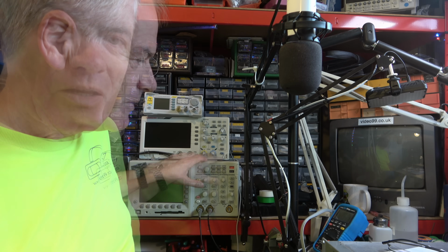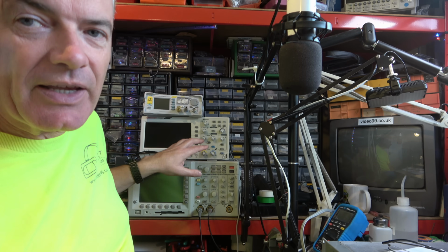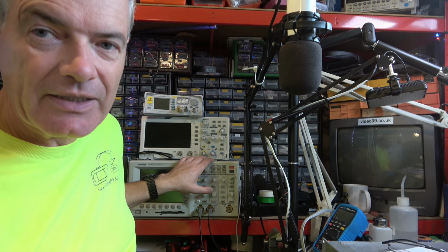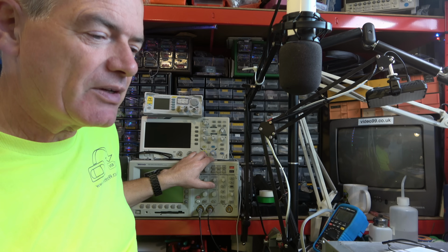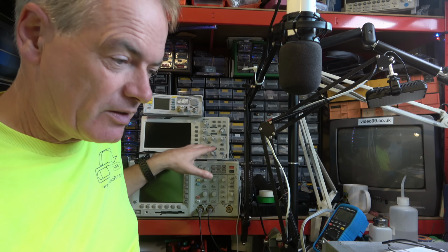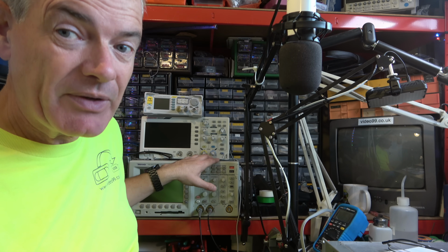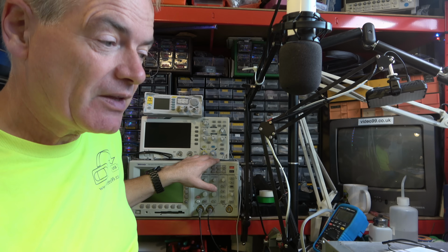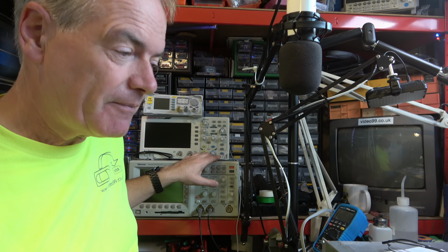I mentioned at one point that we were getting a 0 bug error message on here, and that's due to failure of the Dallas Semiconductor real-time clock in here. I'm going to have to look up which model of real-time clock it uses and where it is, if it's accessible, or let me know if you have already done that. You can get modern replacements to those on eBay and similar.